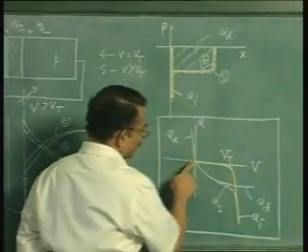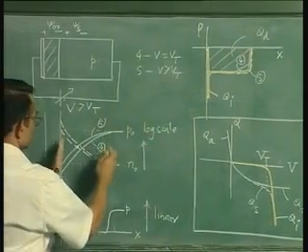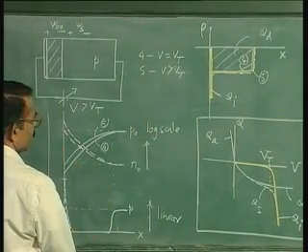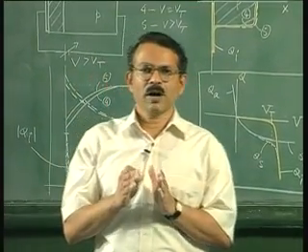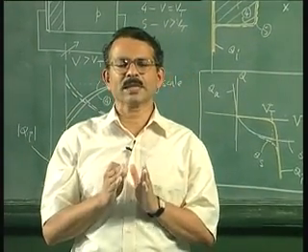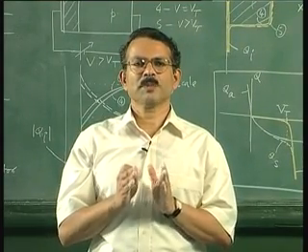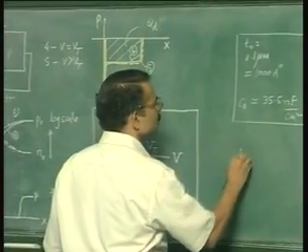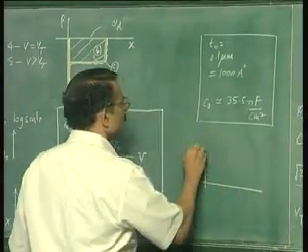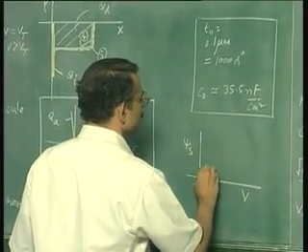Since the depletion charge is almost saturating, or the depletion layer is almost saturating, what we find is that the surface potential, or the potential drop in silicon psi s, also almost saturates at the value corresponding to the threshold voltage. So if you sketch psi s as a function of voltage, you will find the variation to be something like this.